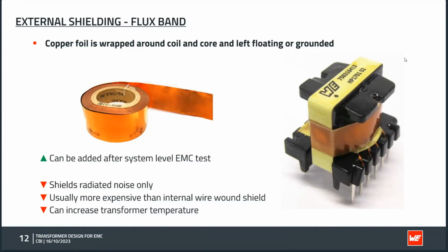It is expensive to add this shield winding because it is a manual process. In contrast to the internal shield winding, now on the external, we can connect start and finish of the foil together. So this one is allowed to short to itself. We usually even add a little spot of solder to guarantee a good connection.